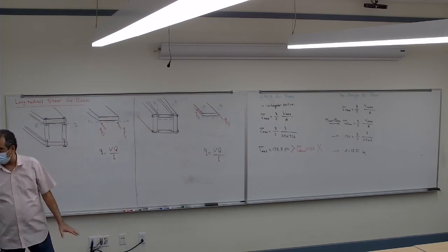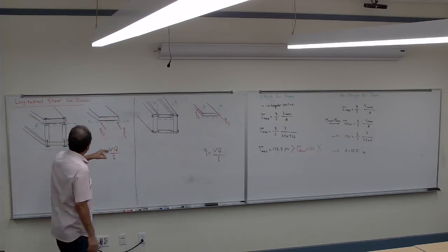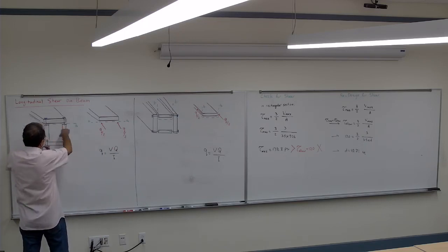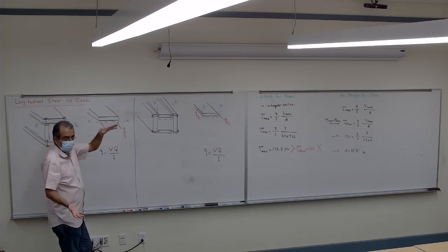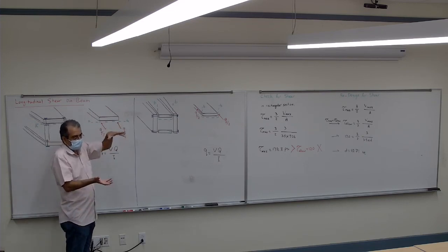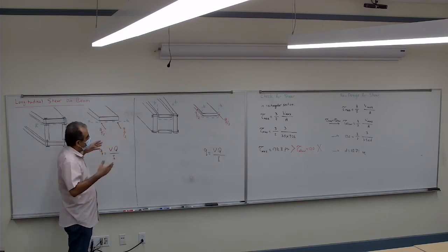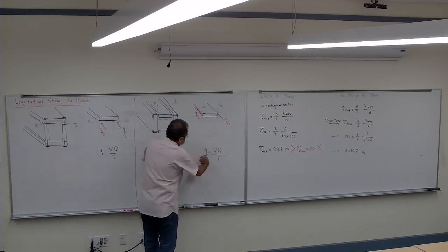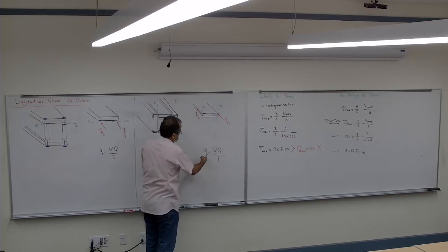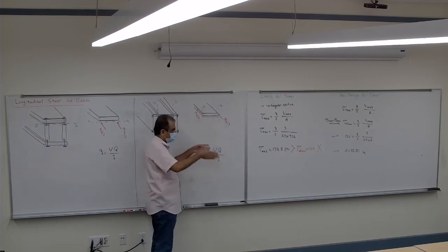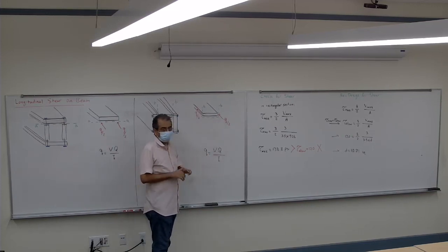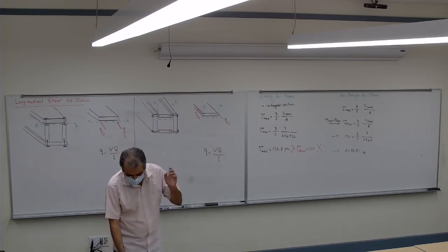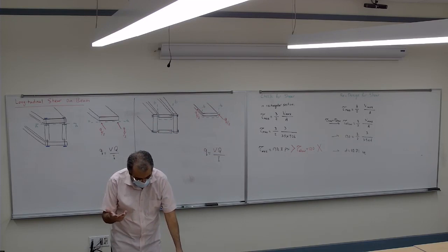So that's the entire idea of how you can calculate it. If you're asked to find the horizontal force, you have to cut it, split it, keep one part, and then just divide the total horizontal shear force between any number of cuts that you have. Do you get the entire idea of how it works?